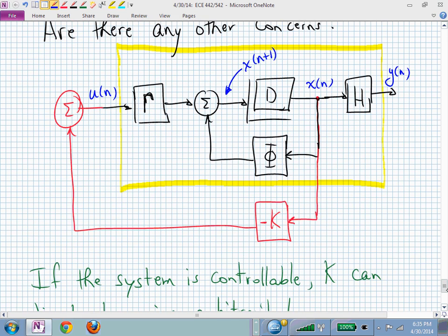What we have pictured right now is a regulatory system, or a regulator design. It just regulates initial conditions. If this was a mass spring damper system and you kick that mass, it would shake and get right back to where you wanted, going to zero with the appropriate dynamics. But you couldn't tell it to move to 2 centimeters or go to 4 centimeters. You don't have that ability. There's no external or command signal right now in this block diagram.